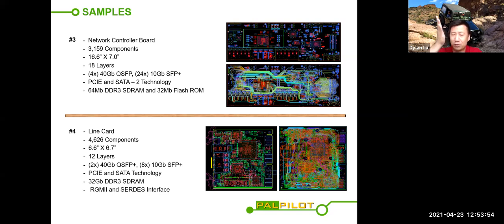The trace cannot travel on this exact same line that is directly above or below you. So routing can be very difficult when all these rules are implied, and then you have so many layers and so many traces that you need to connect them. With good software and a good hand route, you can achieve this type of design. The auto router for this type of board would definitely choke. It will not be able to finish.